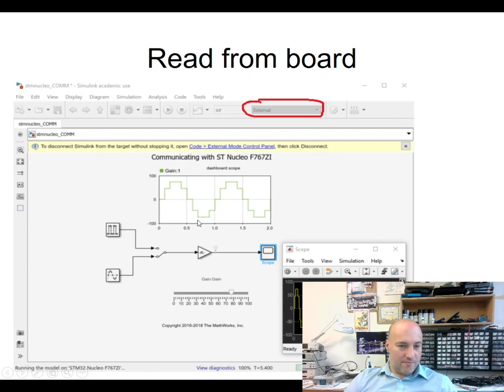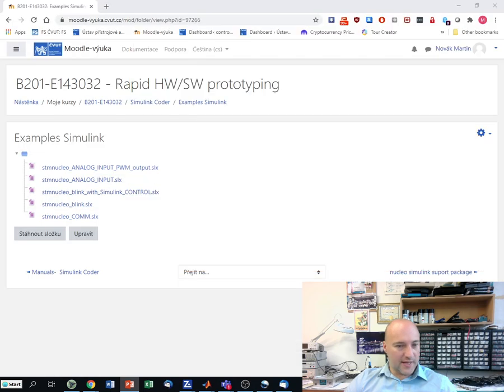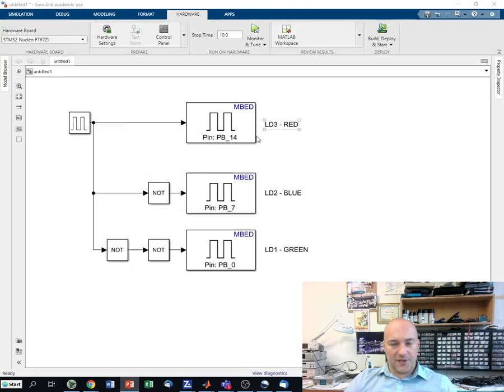Now what we will do for the first try is build this block diagram in Simulink, and we will run it on the PC to see how it's working, and then we will compile it to the board, and we'll run it on the board. So let's take a look at how this can be done. Right now you will not need the board because we'll run it on a PC, but later you will need the board because we'll compile it for the board.